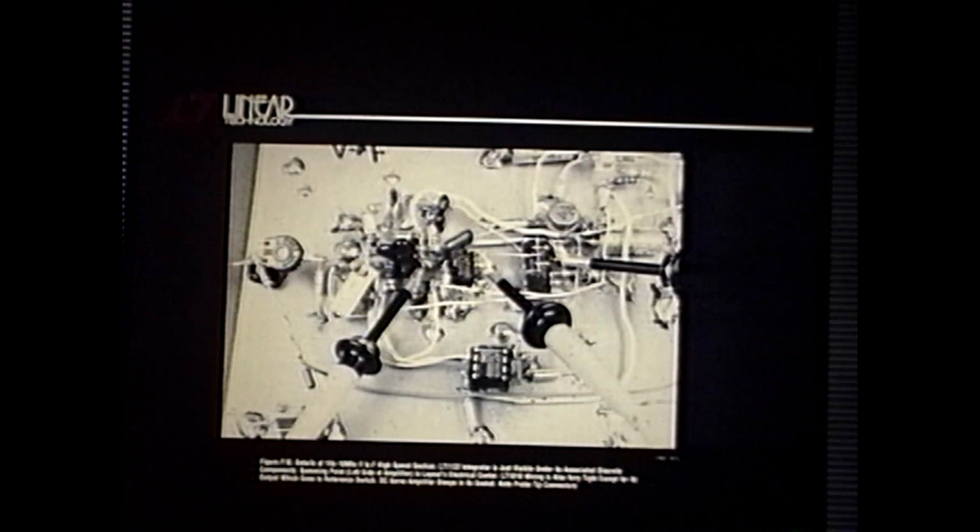This is expanded. Here's the DC servo amp asleep out here through long lead lengths. But the AC stuff, all the summing junction and stuff, is just buried. The lead lengths here are as small as I can make them. You can really see now the tip adapters to keep the ringing down at the point of measurement.